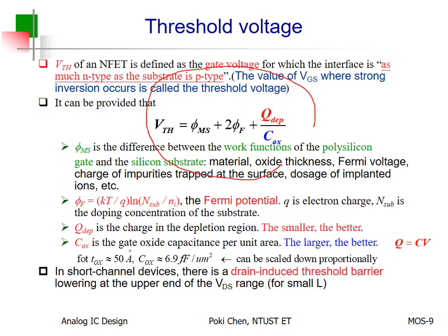Even so, if you would like to derive the full equation, I promise you, it is really hard. After hours or weeks of studying, most of you don't get the point. But within minutes, I help you to understand the most important one. How to reduce threshold voltage? From the very beginning, the channel area needs to be lightly doped. And then, the effective capacitance needs to be increased. But how to increase it?